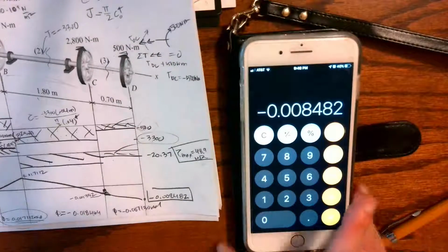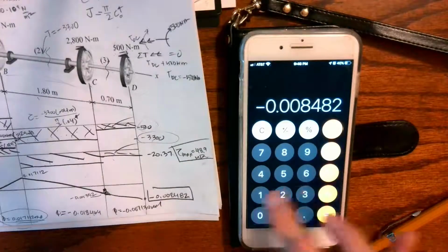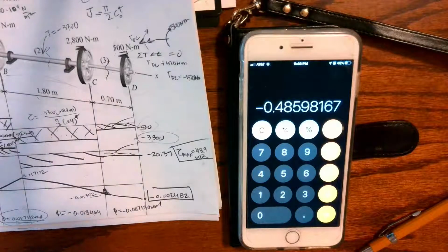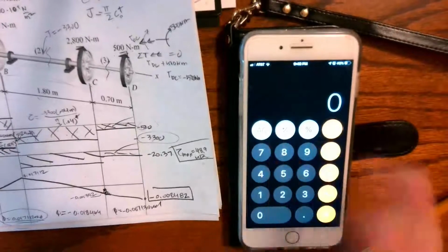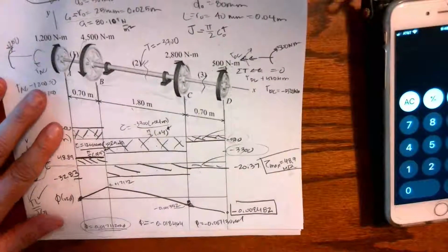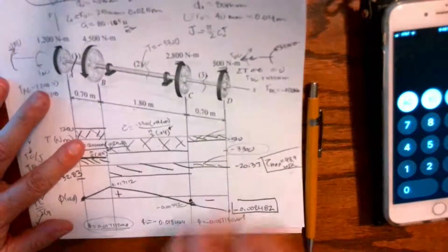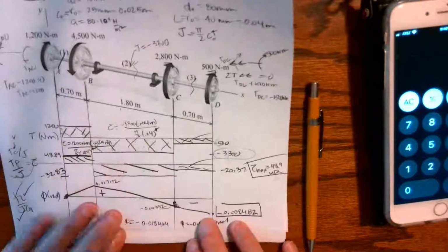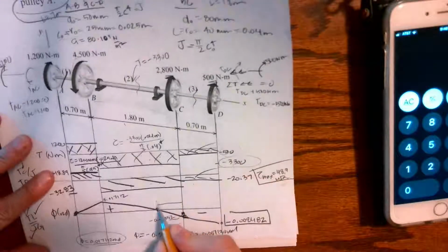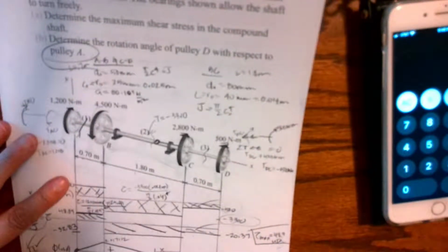And what does that mean in terms of degrees? Well, I can multiply that, if this is radians, times 180 divided by pi, and I get roughly 0.48 degrees. That to me is easier to understand than radians. It also means that somewhere in this part of the shaft, I've gone from a positive rotation, where I'm rotating to the back, to a negative rotation, the opposite. I could actually calculate back that distance to where we had 0 rotation, as we were switching from